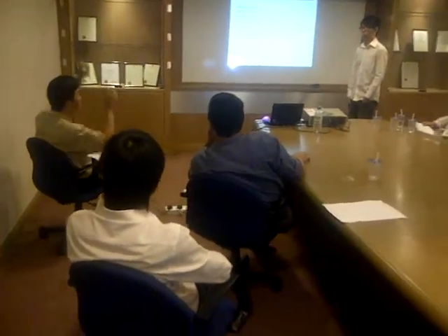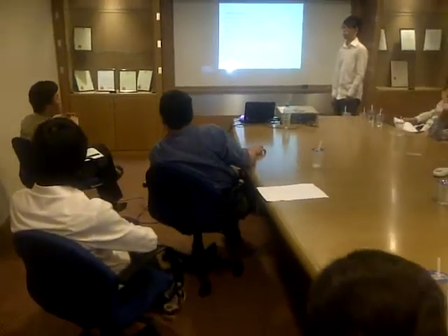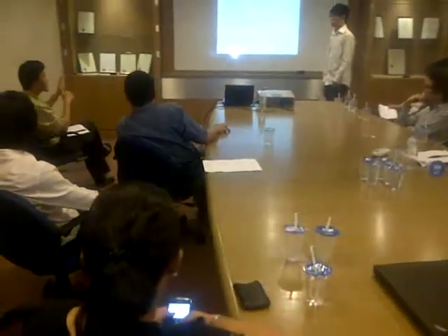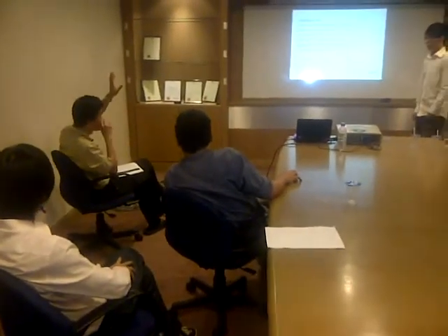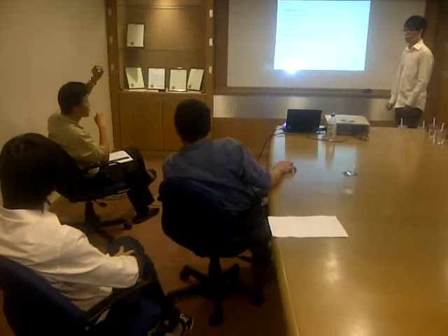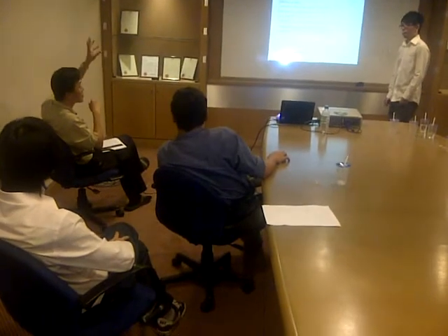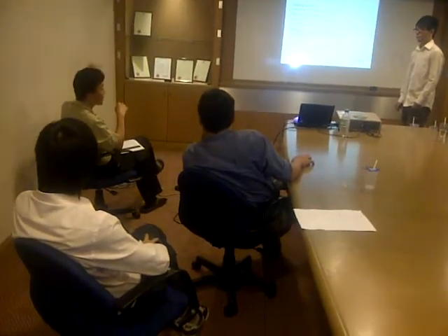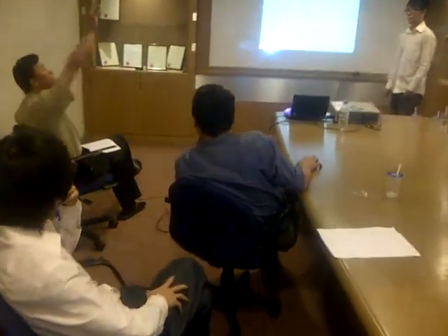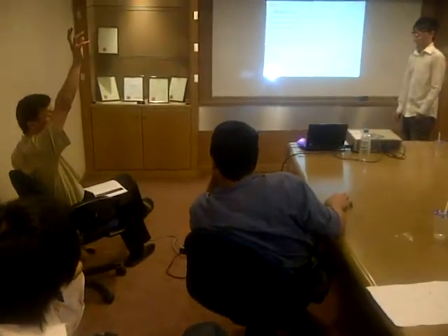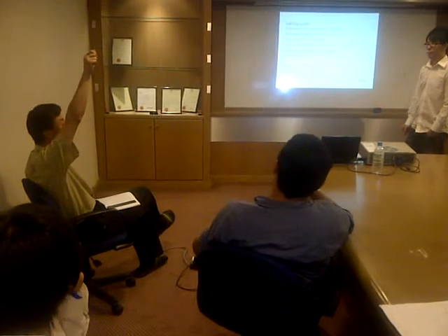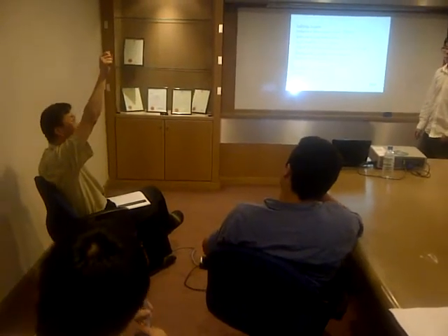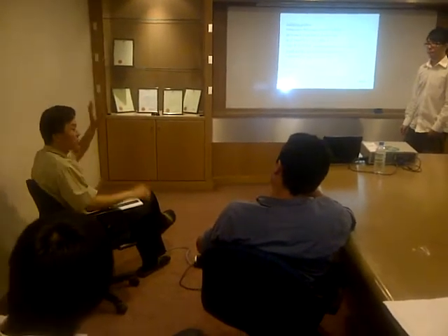Only a wireman can touch live connections. So normal people cannot, unless it is your own household. But there's a reason why for lighting, in order to prevent frequent tripping, we set it higher to 100 milliamp. It means it's something that the general public cannot touch. You are not going to plug your computer into the lighting load, not possible. So it's something that you will not touch. The danger is not there.